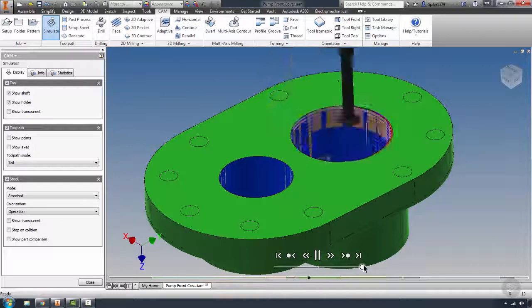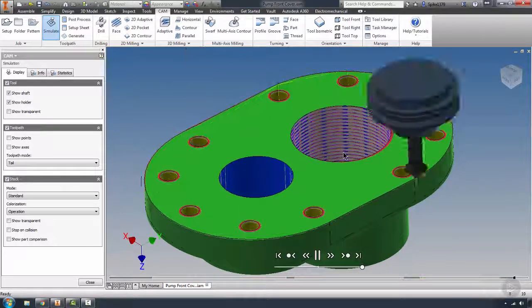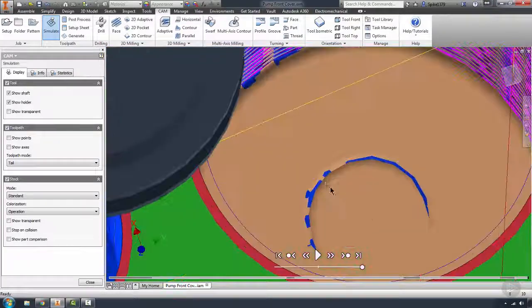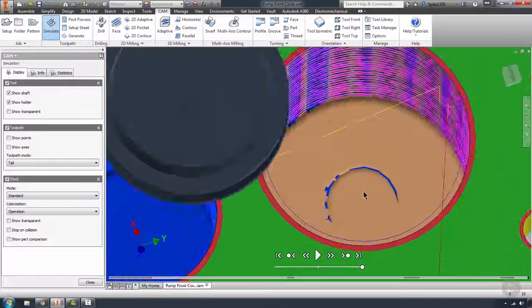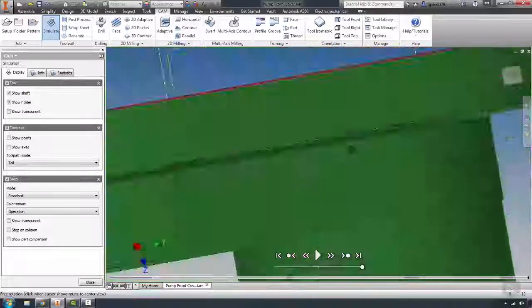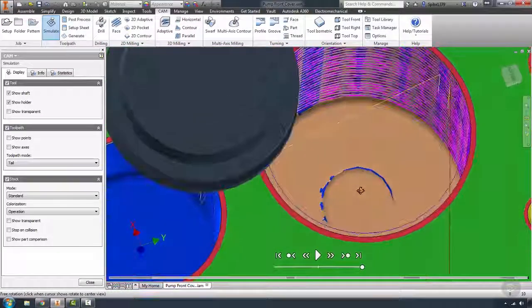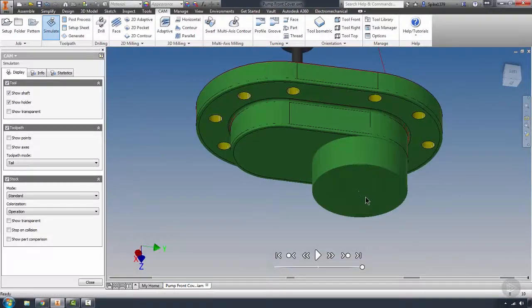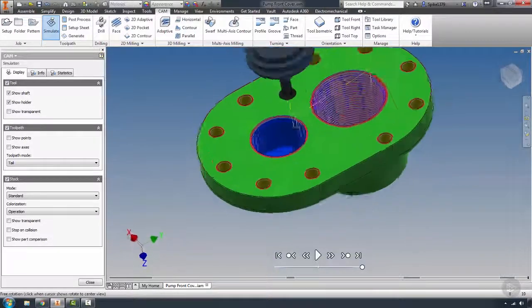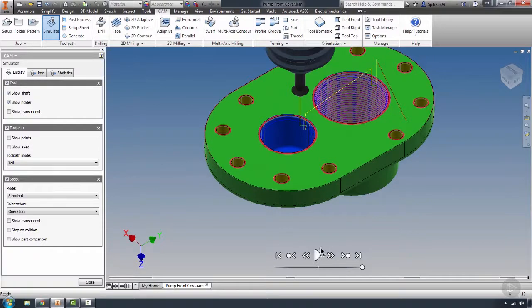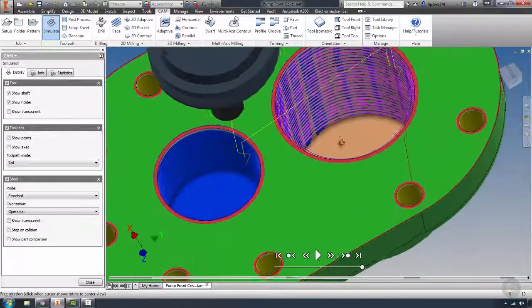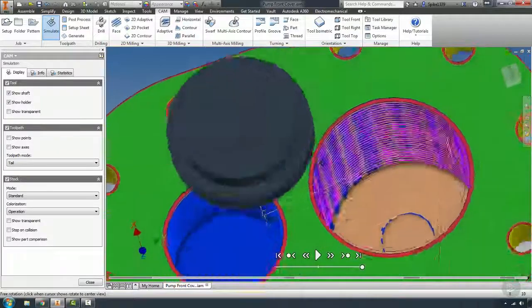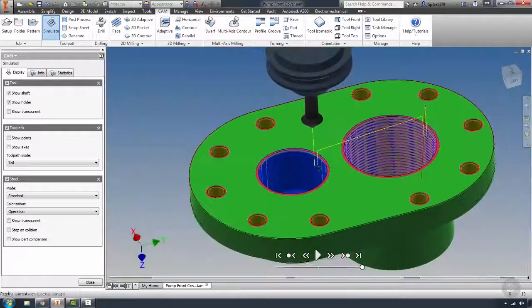Alright, so immediately I saw there I had some stock I need to remove, so there's going to be some adjustment there. I also have what looks like to be a little bit of a swirl at the very bottom of my part. So there may be a difference in the stock to the material. So that op1 stock did not go through. So I'm going to actually have to push that through a little further to clear the casting stock. No big deal there. We can fix that real quick, and then I'm going to have to get rid of that island that was in the middle.